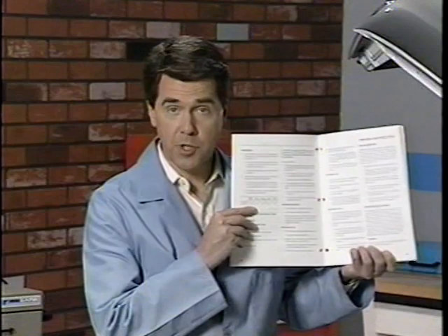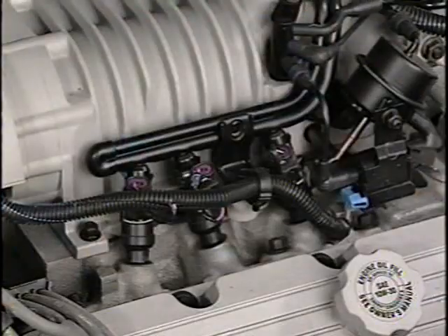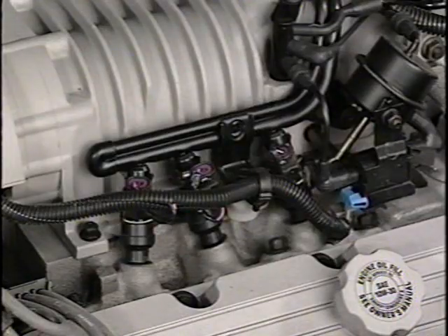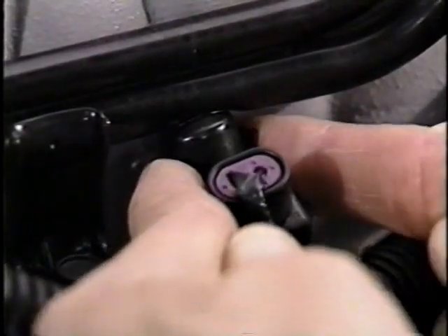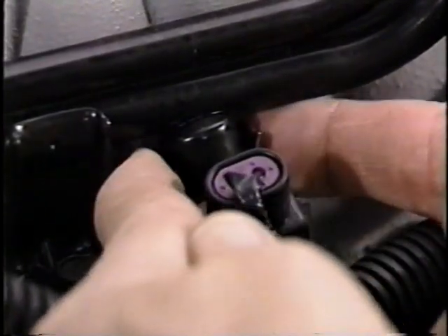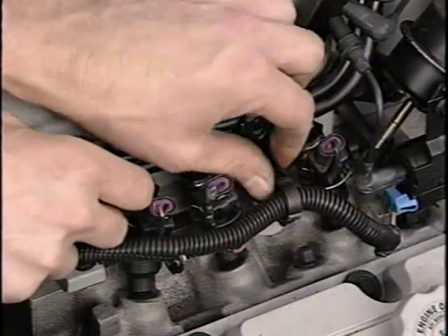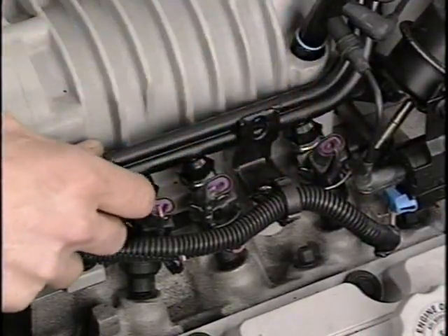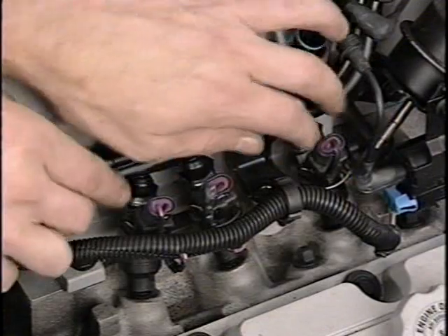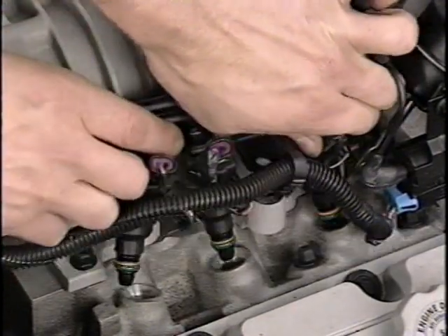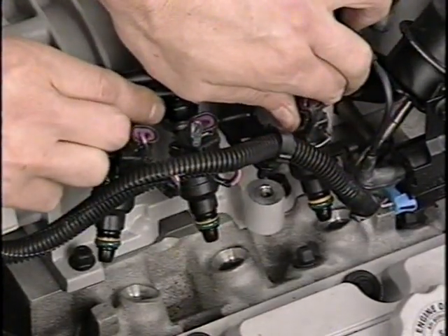In the third section of the reference manual, there are fuel system tests. Included in the fuel system tests is the fuel injector leak test. You should check and make sure the injector retaining clips are in place. Next, you should remove the hold-down bolts. Now, carefully lift each side of the fuel rail, just enough so that you can see the injector tips.